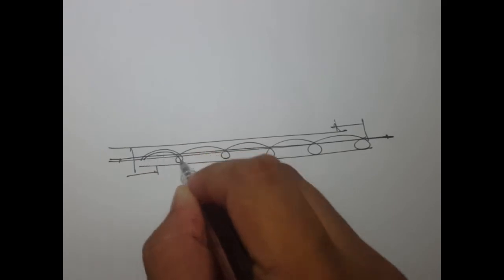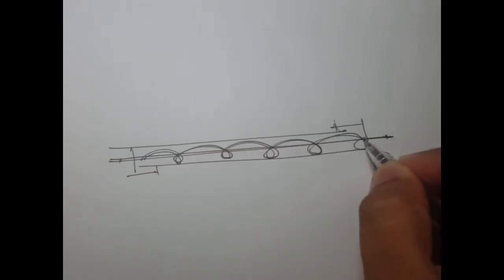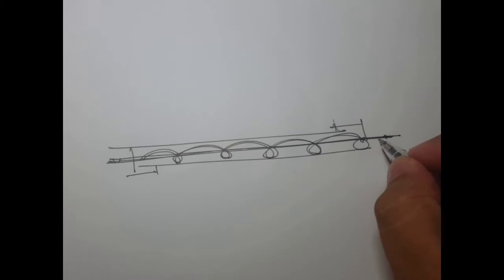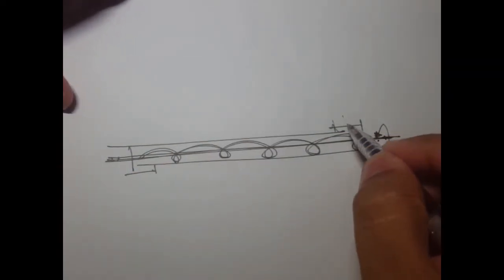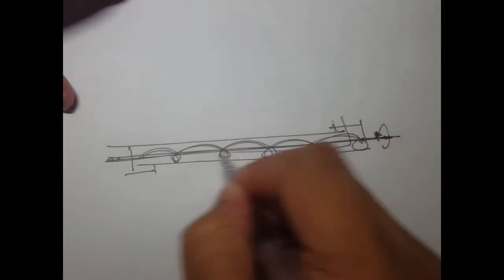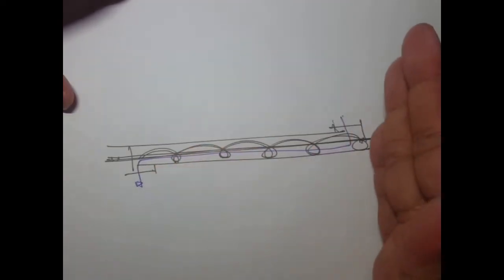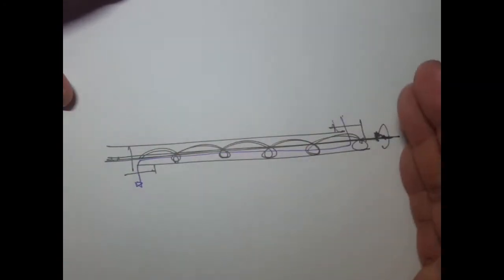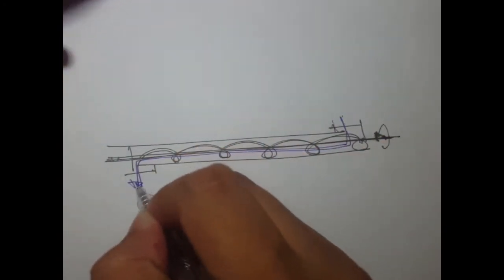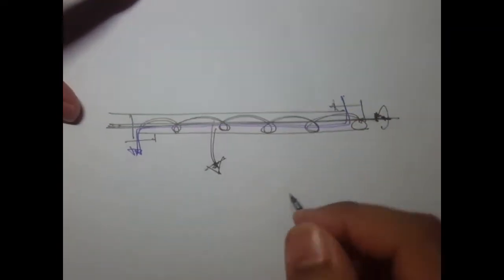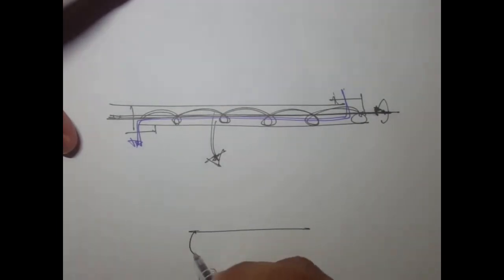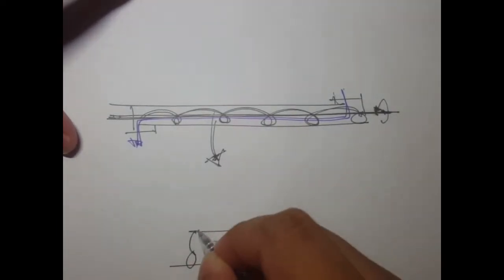Okay, so the screw has a shaft, and then there's a helix. Once this shaft rotates, there is an action on the material; when the shaft rotates, it actually pushes the material to be transported. Now, if you try to zoom in, what we'll see is a shaft, and there's a helix.